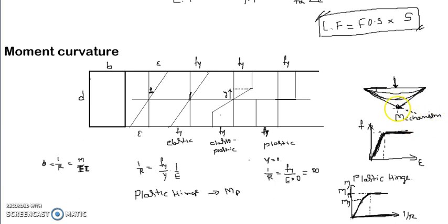So here, once the plastic hinge has been formed, this original member was straight here, but it was curved here because it was still under the elastic limit. Once the plastic hinge has been formed, this is going to be in straight lines, because they are free to rotate here and also here. That corresponding state is what we call a mechanism.